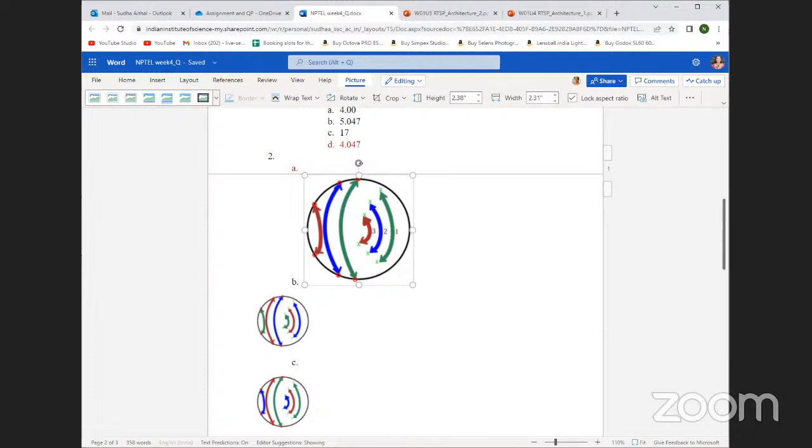We know that IIR filters have existed for more than 125 years, so how the combination has to be done has also been worked out. You can try out combining other ways. There will be a little overshoot from each section, so you may have to quantize them. Minimum quantization across all the sections results if you combine the poles and zeros this way.